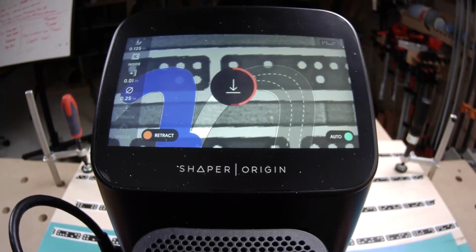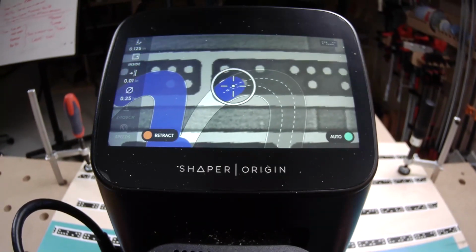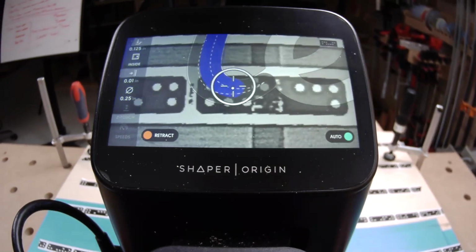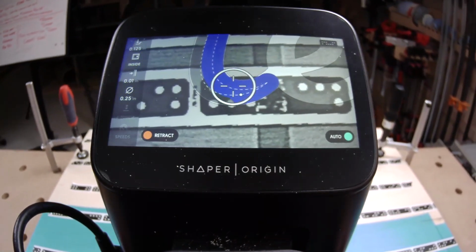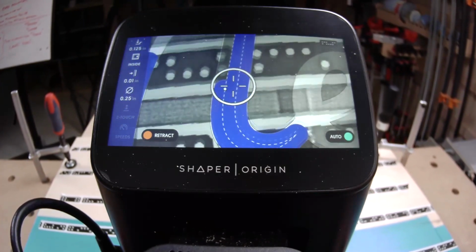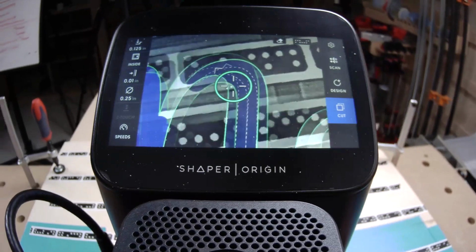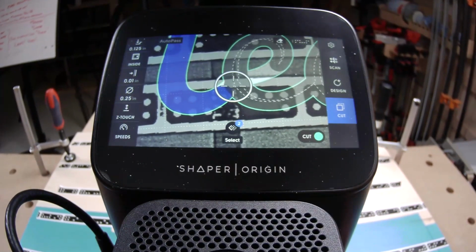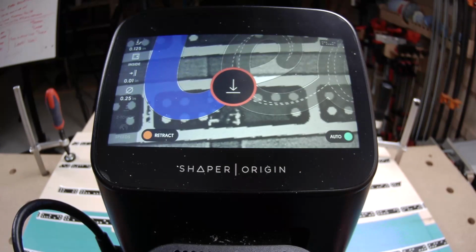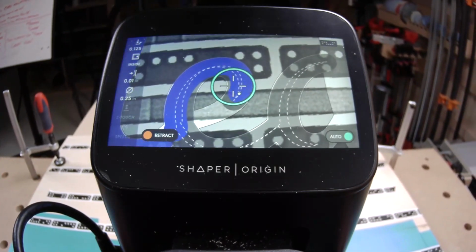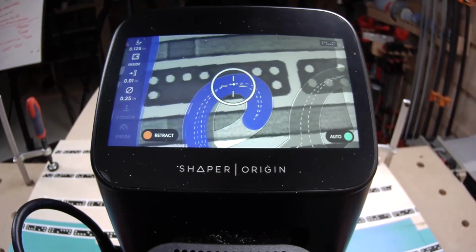But when you're taking really shallow cuts like this, a lot of the time I go even straight to the finishing pass. Because when you're only taking an eighth of an inch of material, it's really not that much, even with a quarter inch router bit. And it's really easy to get really good results. So try a couple of different things, and if you get something out of that could speed up your workflow, especially with signs where the depth isn't that important, I say there's nothing wrong with that at all.